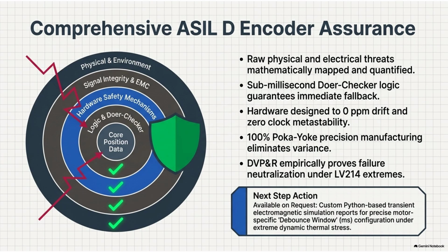Okay, let's just take a breath and recap the sheer scale of the engineering we just unpacked. It's a lot. It is. We started by looking at microscopic cracks in glass and the coefficient of thermal expansion. We analyzed the wide band gap of silicon carbide transistors and how high dV/dt switching creates common mode noise that punches through parasitic capacitance. We looked at digital metastability caused by unsynced oscillators. And the chemistry of fretting, where oxidizing tin and copper.